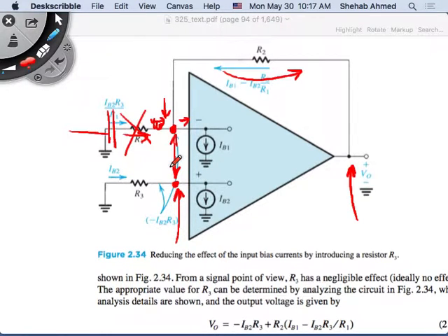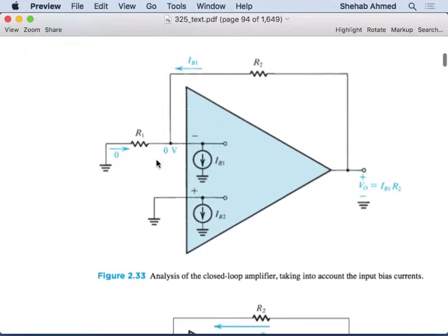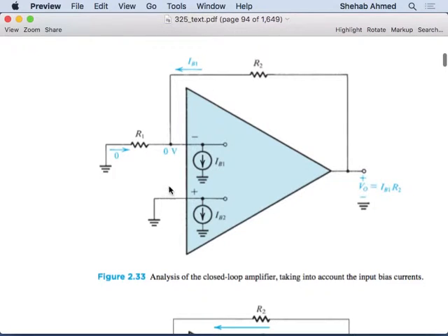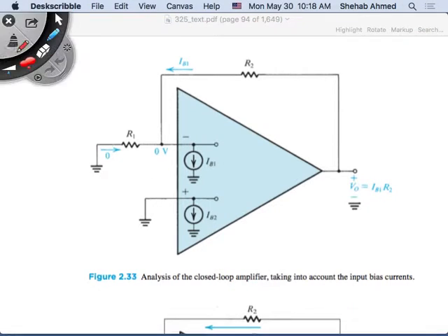right? So in the previous case where I did not have this resistor, this voltage was 0, so the output voltage was equal to the voltage across this resistor alone. Now, when I capacitively couple here, it's like opening this circuit completely. It doesn't exist, right? But here, I added my resistor R3.